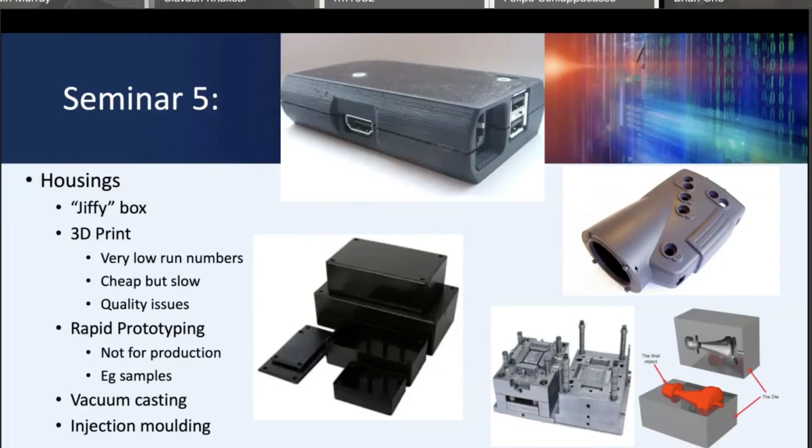The top way, if you've got very large quantities of things to make, is injection molding. We've got an example of a chess piece here that's injection molded. Basically, a machine works liquid plastic, or liquid material, into the mold, and it forms the shape that you want to produce, and that can be done for boxes and things as well.